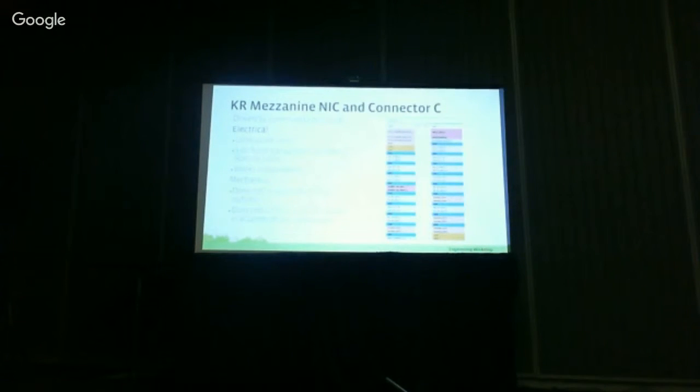And then last year in the community, I heard common interest, mainly from Intel and Quanta, in having a more dedicated KR interface, and their requirement is that they want to have sidebands. Maybe from a chipset or from the NIC they have some native sideband, and they want to talk to the PHY on the KR Mezz. Connector C is the answer to that question.